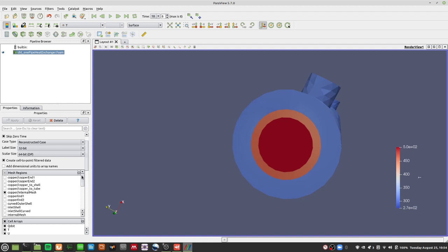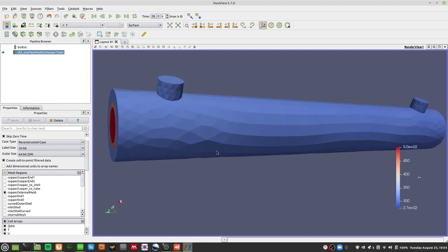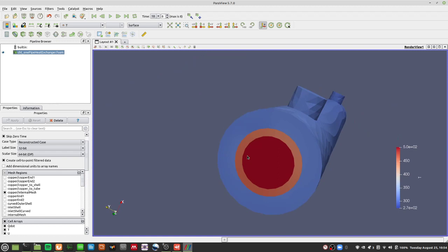And of course this simulation is done with a coarse mesh, so it's not as physical as it should be, because I didn't add the boundary layers, but it's numerically stable, doesn't go off the bounds, so that's the good thing.